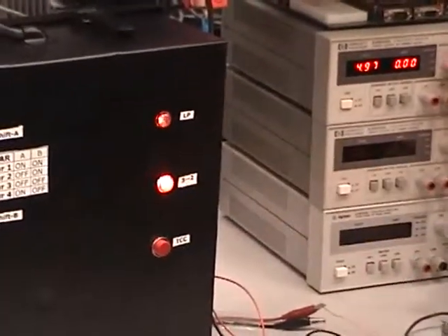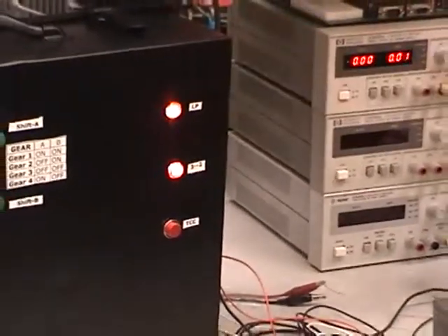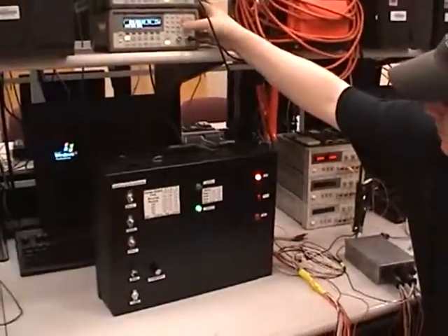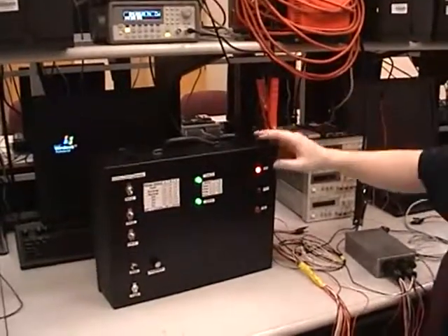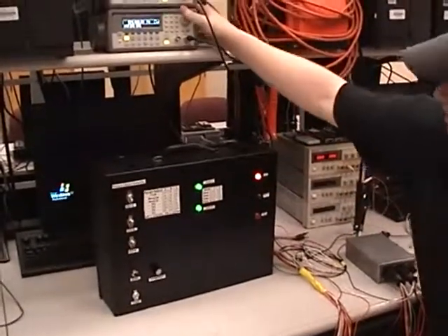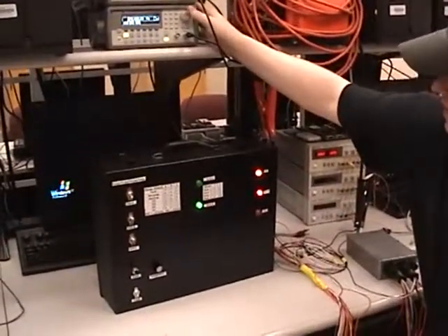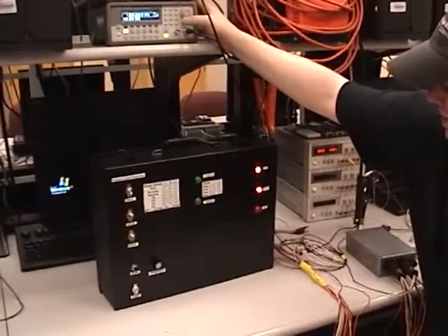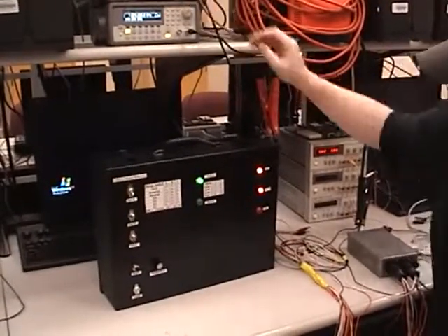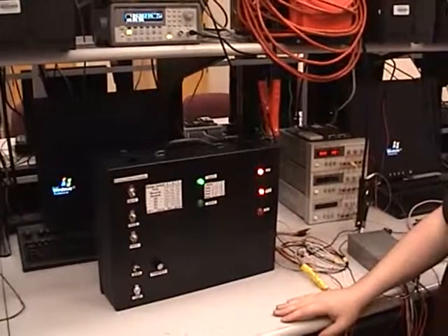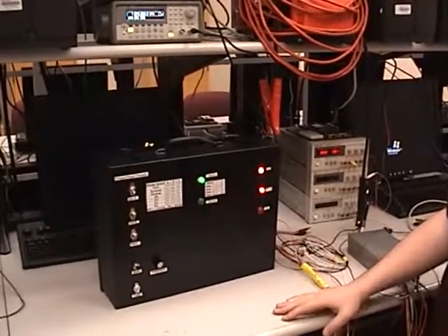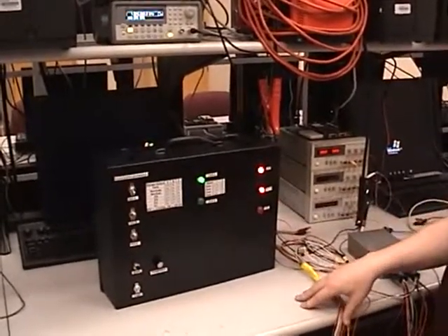The 3 to 2, right here, we can show you that the 3 to 2 is off in first gear, just like it's supposed to be. And then as soon as we switch to any other gear, second, third, and fourth, the 3 to 2 goes to a 90% PWM. And that's exactly what we would expect.